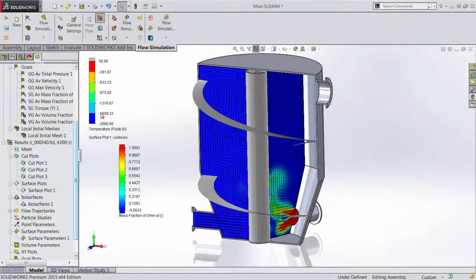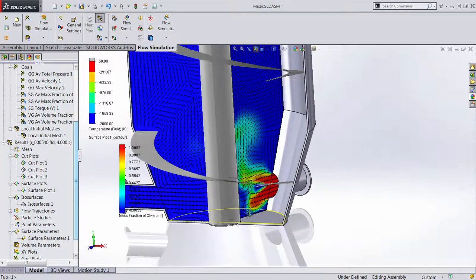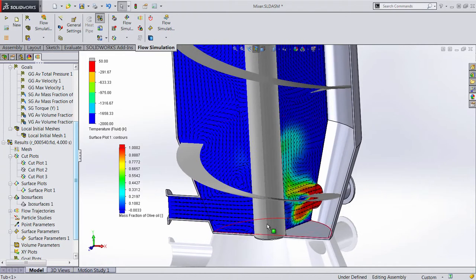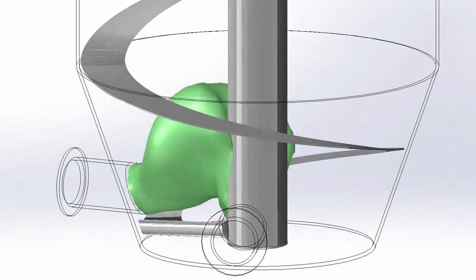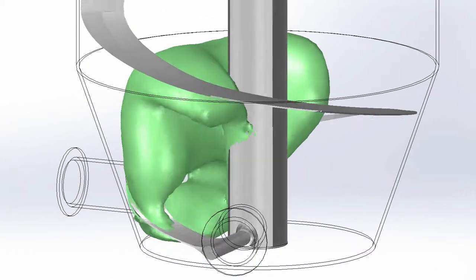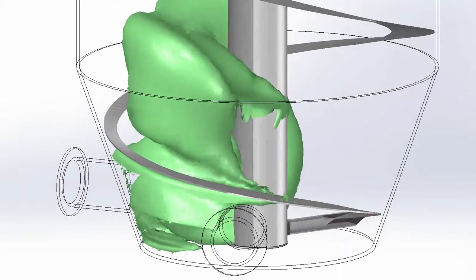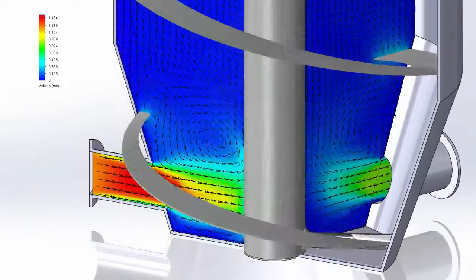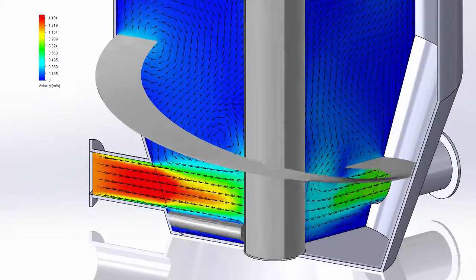In this mixer, we have one fluid being blended with another, and can visualize concentration distribution variation with time. These time snapshots can showcase interaction between the rotating blade and the added fluid. And again, visualizing results through the animation delivers far more understanding. The new rotational sliding mesh capability enables you to accurately and easily evaluate time-varying flow performance of your design.